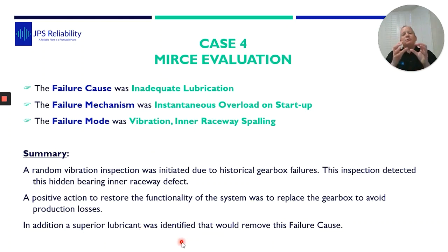This is a type of oil that, when the gearbox stops, has additives in it and actually sticks to the bearing. So it reduces the probability of the instantaneous overload and the damage to the bearing. And in some sites where we've done this with this particular oil, it has eliminated an inner race defect on this particular model, which we found seemed to be a bit of an issue.